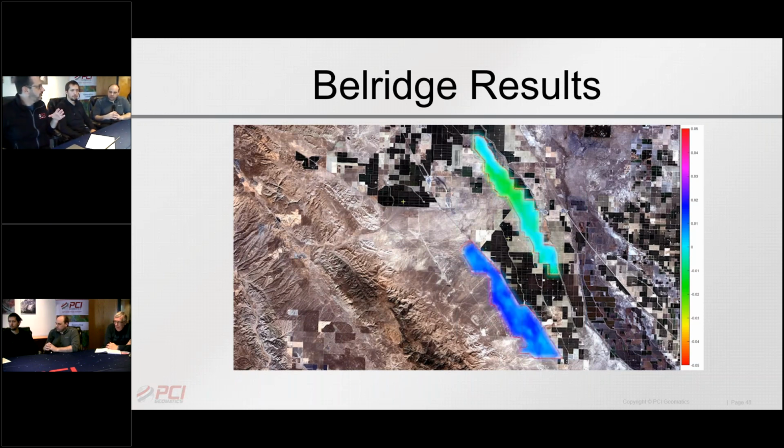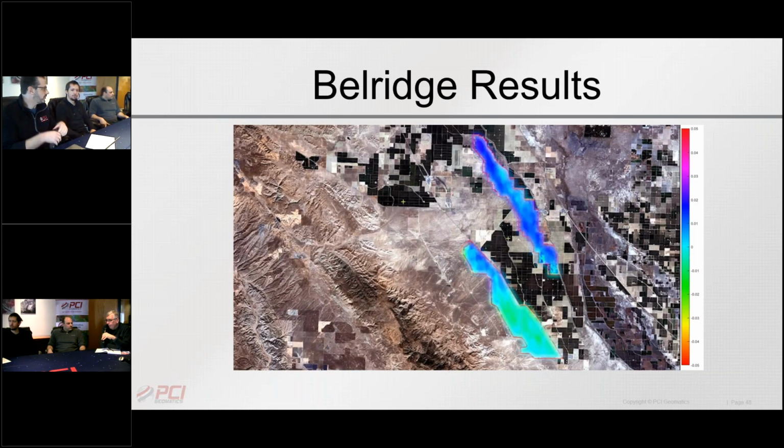So if it's accelerating up, that potentially means the steam pipes are in danger. Or if it's moving too far. The key thing with velocity is you want everything to be moving up and down at the same rate. Otherwise, you put a lot of strain on the pipes. So if one part is going up much faster than another part, there's a lot of strain on the pipes. The spatial pattern and the rate of change are the two key things people use this technology for. If it all moves up together, that's better than if part of it is moving up and part is moving in the opposite direction.